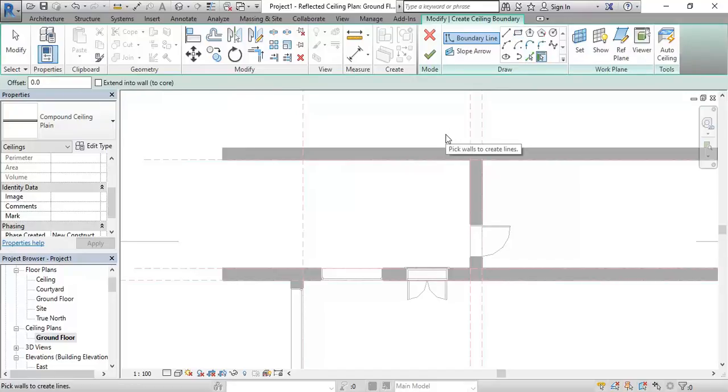So I'm just doing the kitchen, so you might not have a kitchen ceiling, you might have only done the bathing space, so it's good to have them as two separate ceilings. You've got to click on the ceiling tool to do that. So it's just on the architecture tab. And then you'll see you've got the option on the right to sketch ceiling. But I'll come and show you in a second. I'll just finish this off.